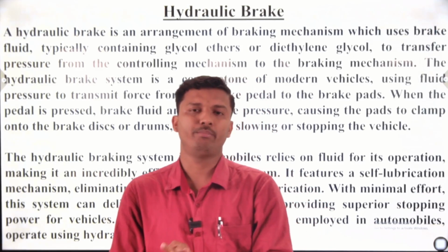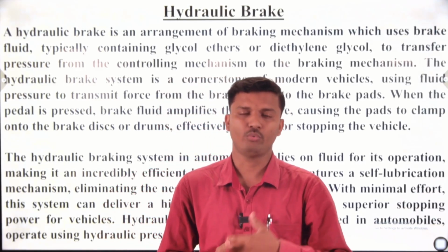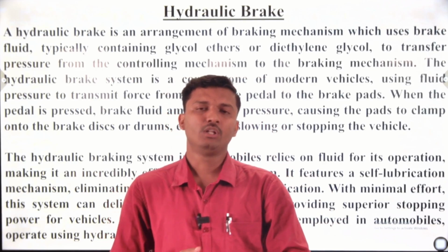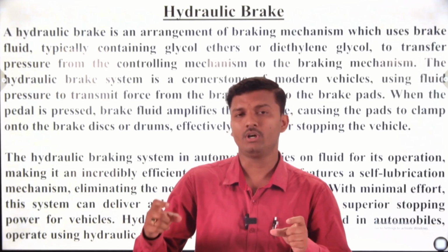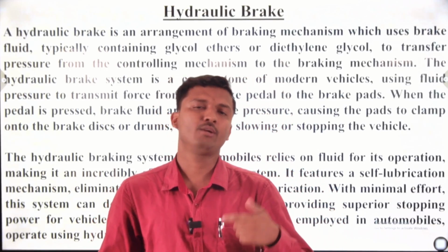After the brake is released, the same principle occurs in reverse. The fluid comes back to the master cylinder, the piston is released, and the brake shoe is no longer in contact with the brake drum, so the vehicle can move forward.